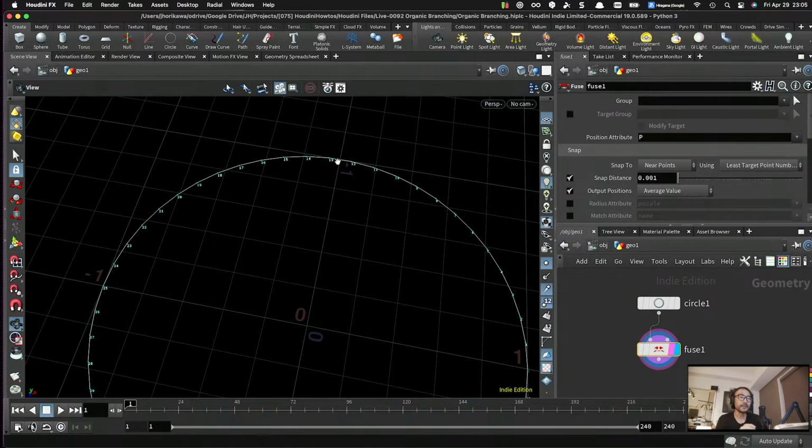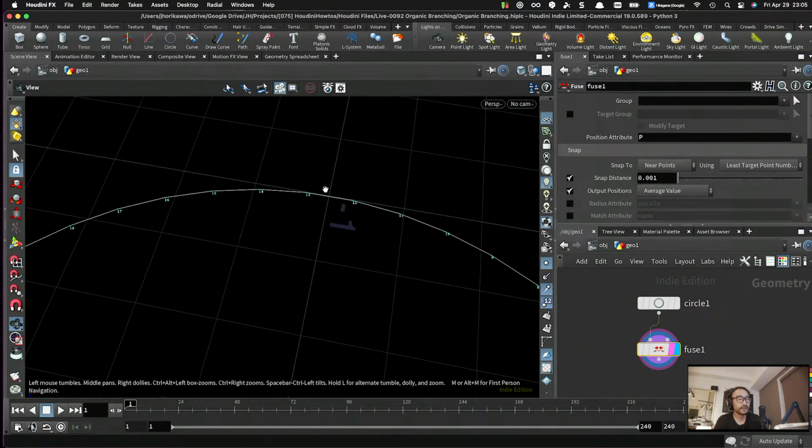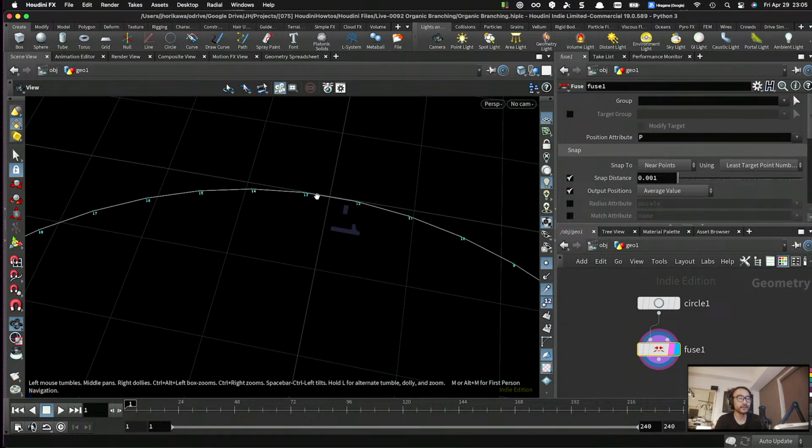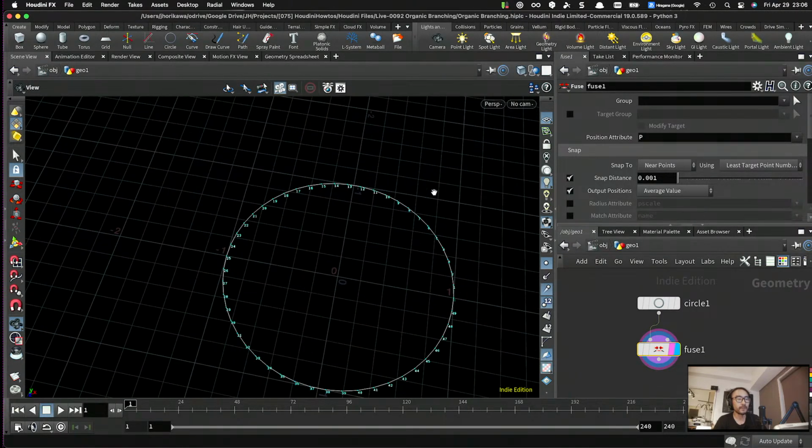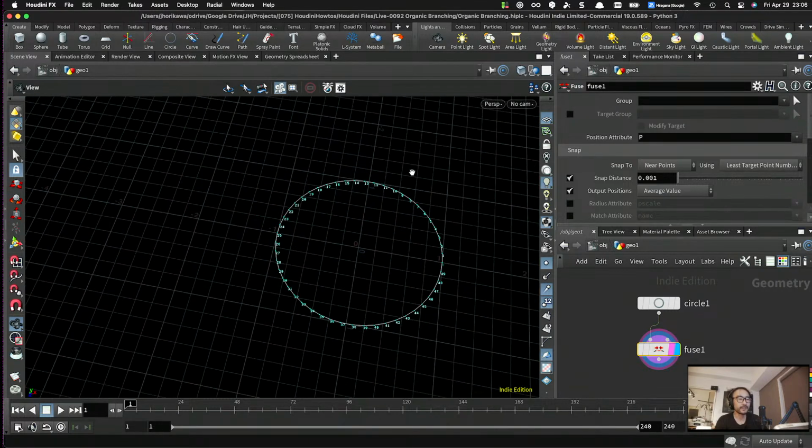So using kind of a stretch or spring force using Vellum. When you do that, the force tries to repel those points in the opposite direction to make this length bigger. So for this edge, this point will try to go this way, this point tries to go this way. All the other edges are doing the same thing, and as a result, all the points will try to go outward, equally in this case, if it's a circle.